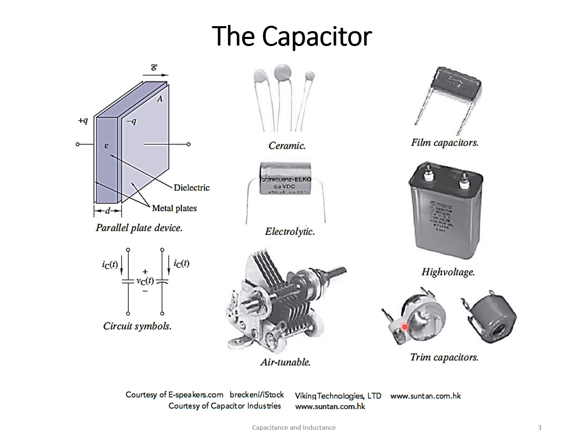And the last type of capacitors shown in this slide are trim capacitors. Basically, we have D-shaped parallel plates, and in between there is a dielectric material. It's a plastic paper type material, and we can adjust the capacitance with the help of a screwdriver.